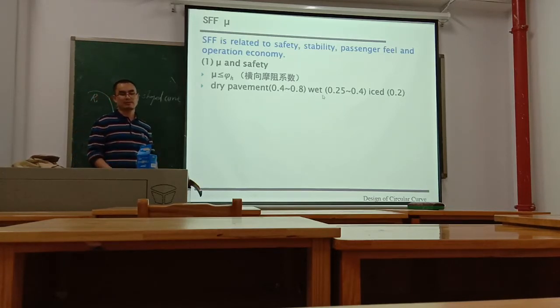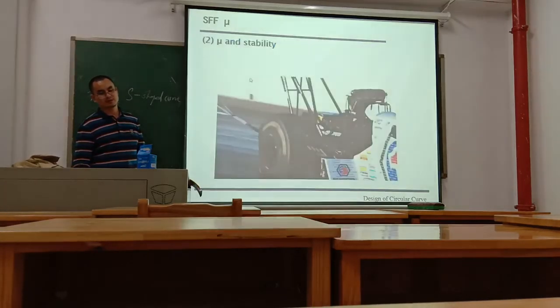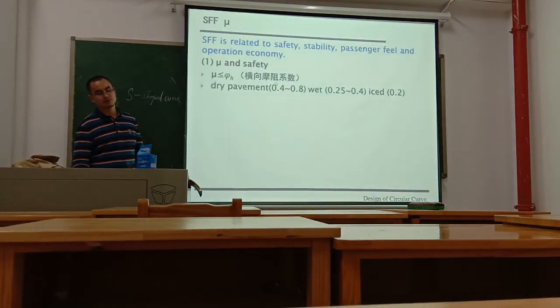On wet pavement, it is 0.25 to 0.4. On icy pavement, the adhesion factor is 0.2.